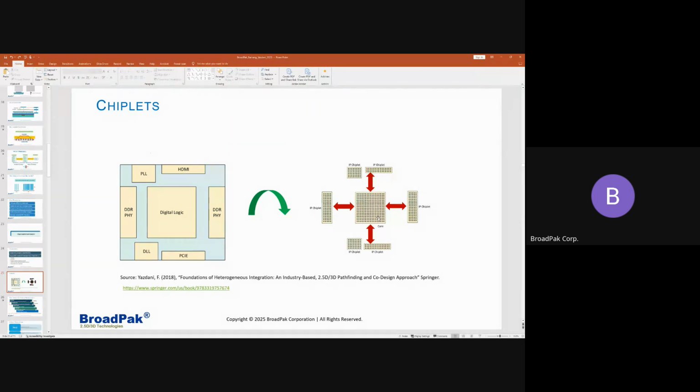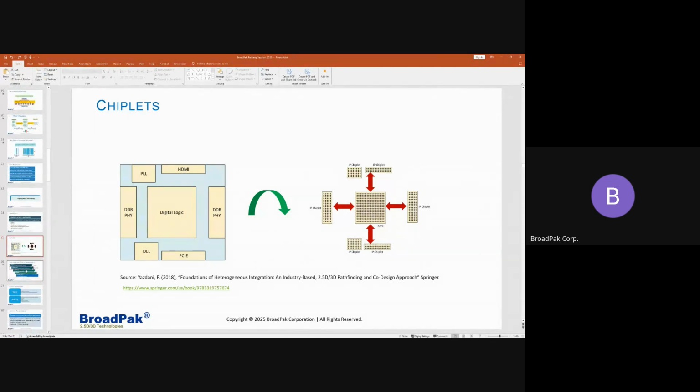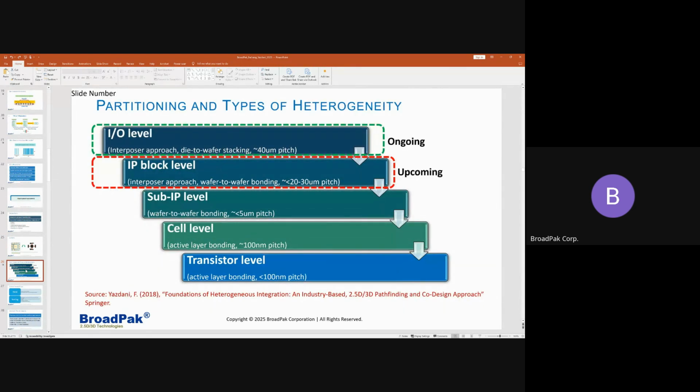You can take advantage of both worlds to shrink your core, to go to a lower process node, and then to reuse the IP. So one of the things that the chiplet does is basically IP reusability and faster verification and time to market. These are already tested, verified components that are going to be mounted on a substrate and are going to communicate with the logic die. All right. So how you partition your silicon from a monolithic to a chiplet is going to be important.